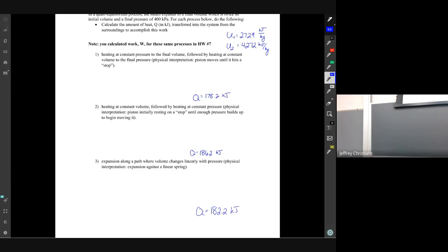I just want to make sure I got W right. W is just your pressure times your change in volume. Yeah, so it's the picture that you drew, it's the area that you shaded. You should get 3 different values. It looks like you're 25, but yeah, 23. That's right. Other people got 23.